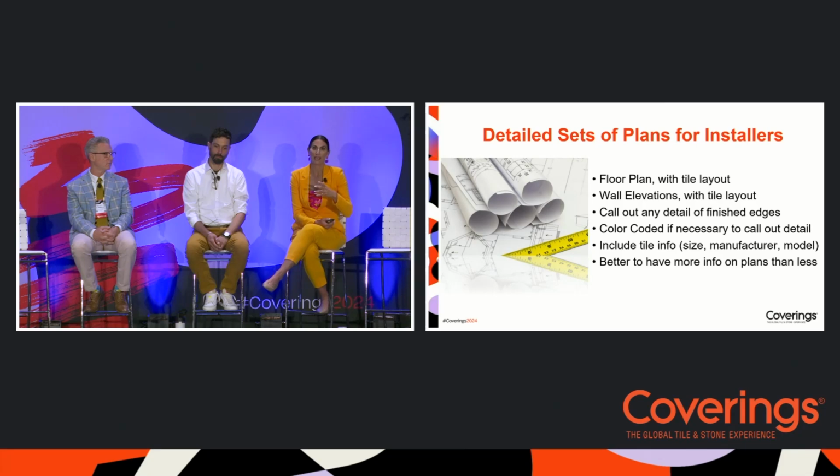I think, for me, sometimes just a very basic layout is great, but giving as much information as possible, letting the tile size in the key, tile size, manufacturer, model, all of that info. It's best to have more than less, always when it comes to your tile plans. For the wall elevations, it's the same thing.